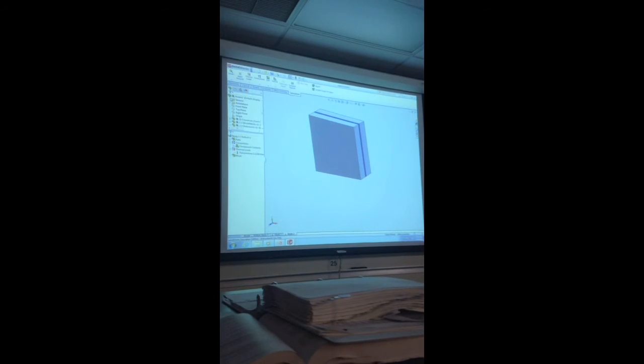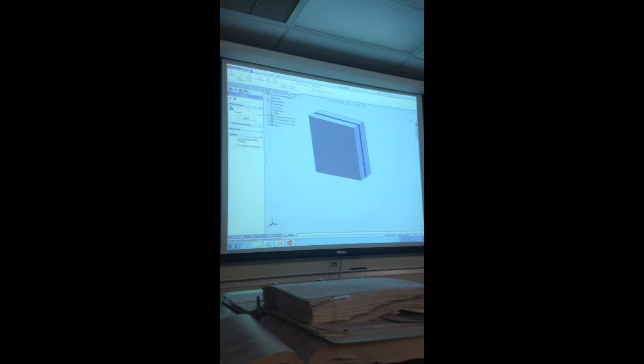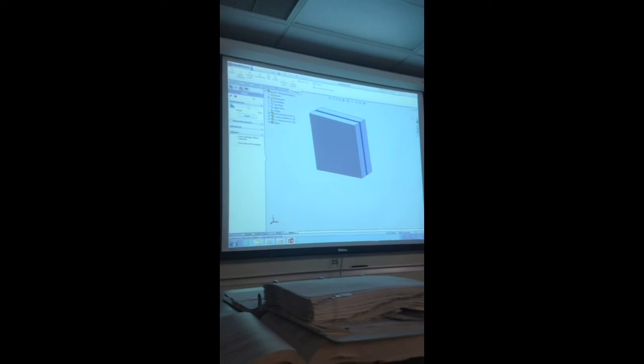Any questions, sort of how you set this up? After you run a study, well, you have to create a mesh. You get a slider bar, that's all you get. You don't get to see the mesh size. It's just finer, takes a little longer. Coarser, a little easier. You might start off with a coarse mesh, so it goes very quickly for a short period of time, but you're going to have to run this thing for like a minute, right? Until you start doing things like changing your heat flux. At any rate, you do all this after you have all the boundary conditions in, you hit run, and then you'll get a set of results.